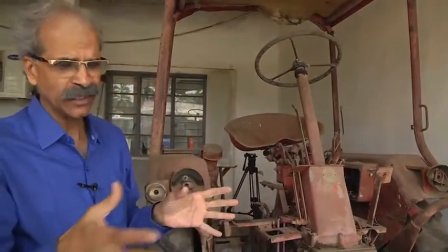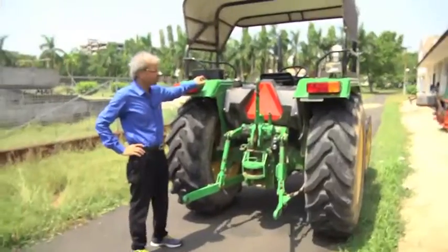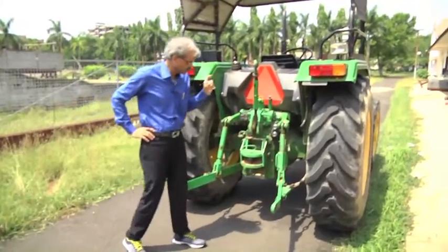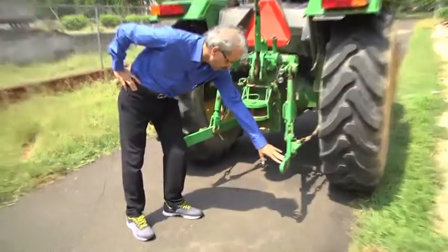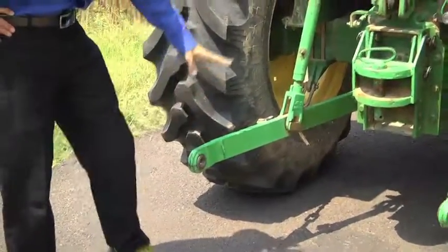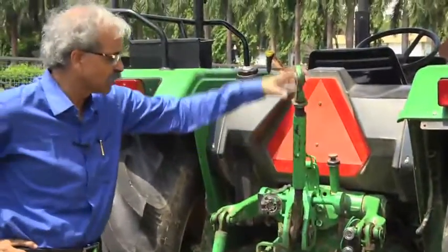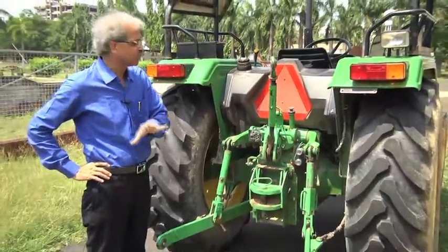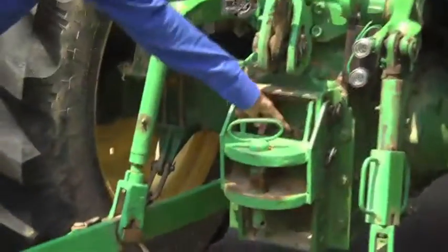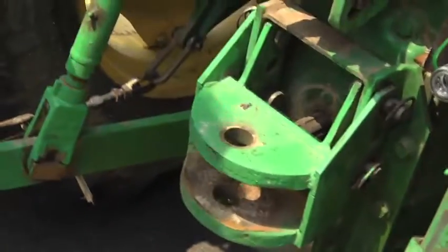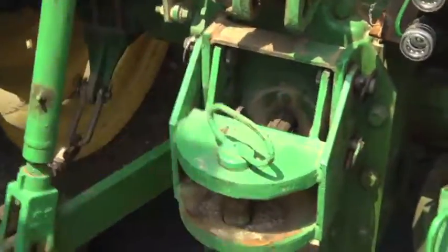Now, when you go to a new tractor, have a look at that. So, you have a look at the new tractor today. We have 2 points as I showed you there. Now, here there are 3-point linkage. This is the first point, which is a lower link, then this is another lower link, the second point, and the third one is this top linkage, which is the top point. So, these are the 3 points which are there for attaching the modern implements in those modern tractors, and the PTO is here, which is a back PTO. Now, it has also a single link where you can attach the trailer, where this is the pin here, and we can attach at these 3 locations.